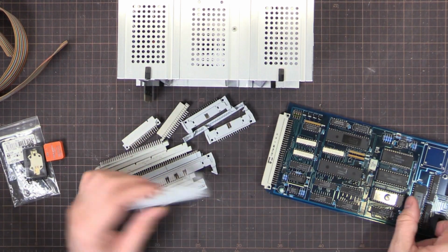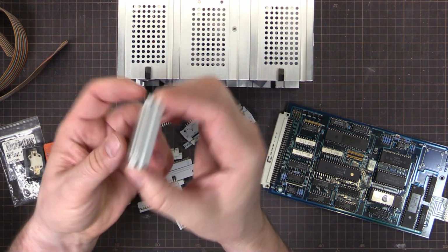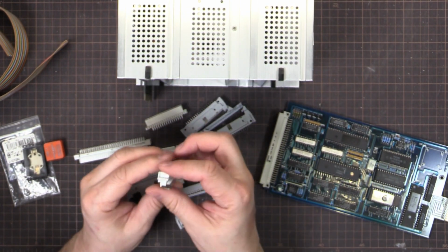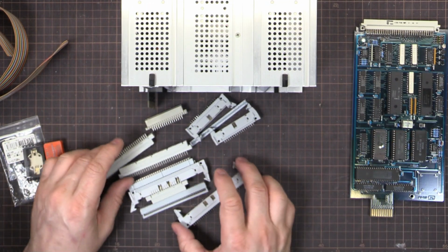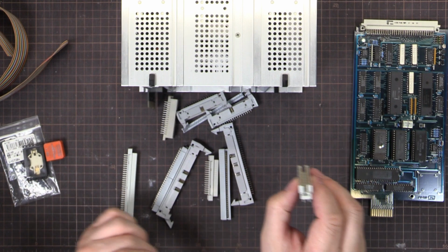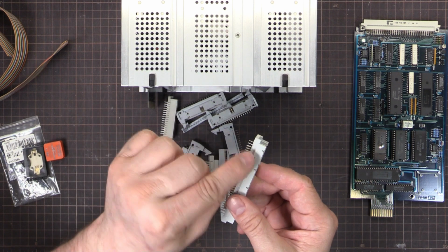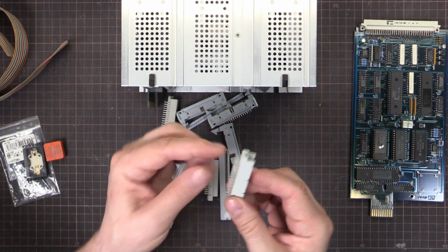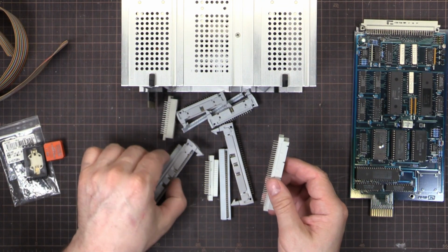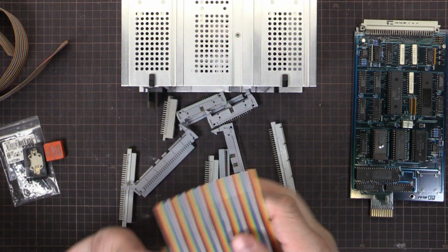Anyway, I want to make the extension cables. So I've got a bunch of connectors to do that. I've got my backplane connectors. I've got a 90-degree one there. That's actually for an option card. I want to make that, so I bought the connector for it. So what I've got is a big chunky connector. That one's going to go inside. Then I'm going to have an adapter PCB, just a little strip PCB with the contacts coming across on both sides. I'm going to put the PCB not like that, but like that. Then to connect to my ribbon cable, which I've got some big chunky 64-way ribbon cable for this one.